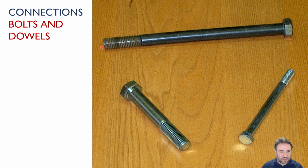But whether I get a ductile failure mode or not depends on the geometry of the bolt and the geometry of the members. With larger bolts, we're likely to get some kind of brittle failure mechanism in our connection, which means a failure that generates cracking in the wood and basically instantaneous failure after the cracking.